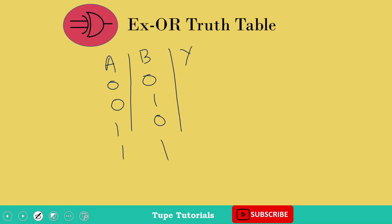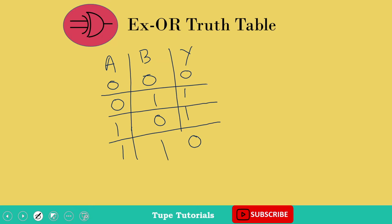Now as per the XOR logic, if both the inputs are high or both the inputs are low, then the output will be 0. Here both the inputs are low, so output will be 0. If one is high, other is low, the output will be 1. One high, other low, output 1. If both are high, then output will be 0. So this is the logic of XOR truth table. You have to remember or understand the logic of the XOR truth table because it is required in gray to binary and binary to gray code conversion.